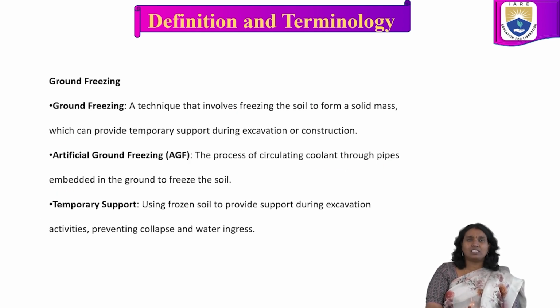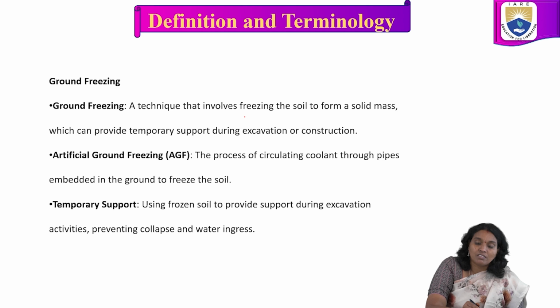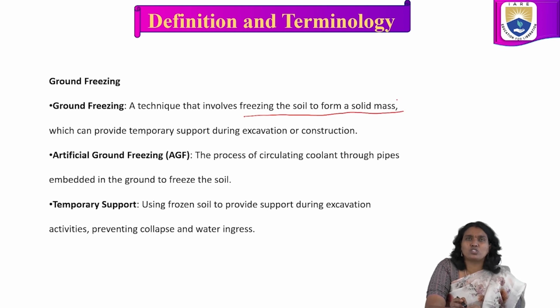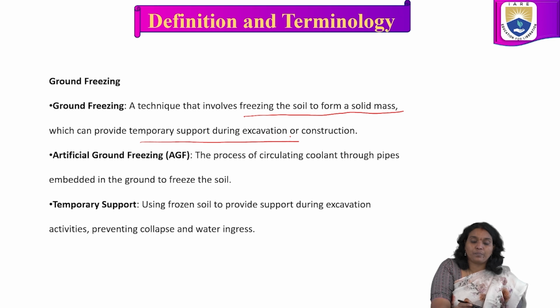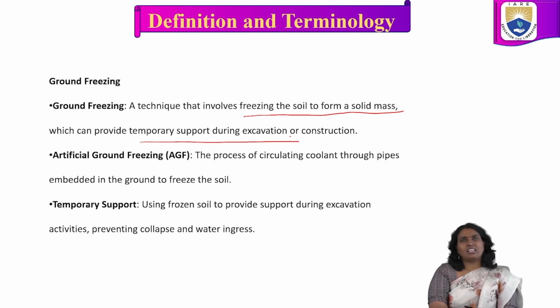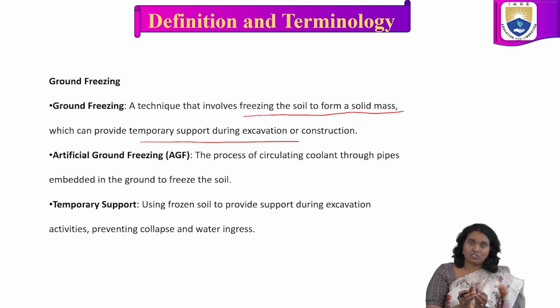In ground freezing, different types are there. Ground freezing is a technique in which we freeze the soil to form a solid mass, which can provide temporary support during excavation or construction. In some situations it is also considered an impermeable barrier.